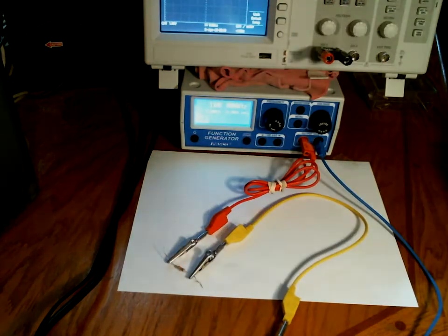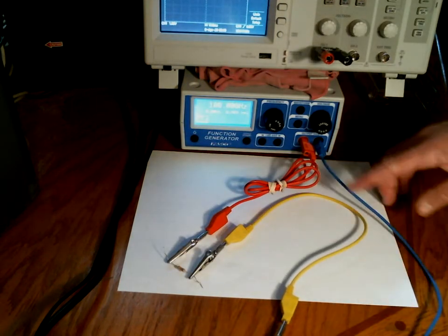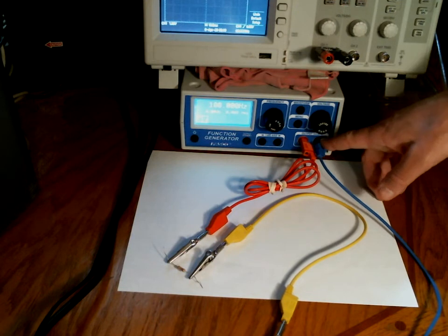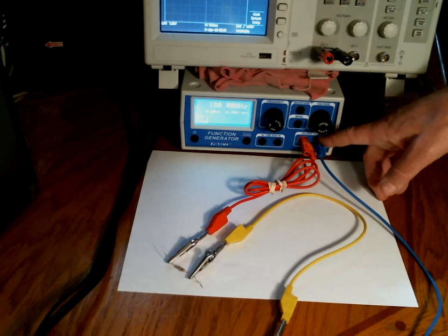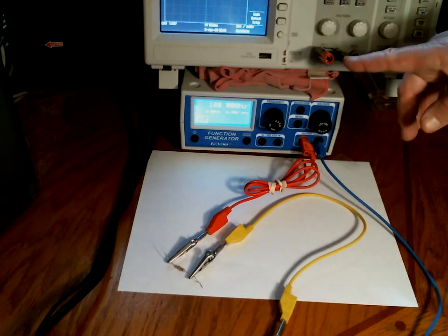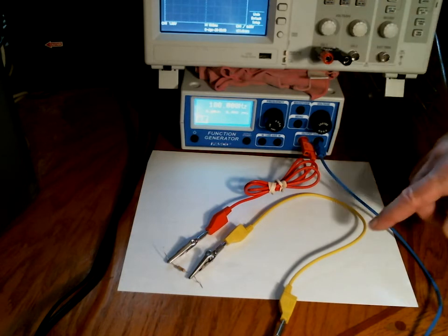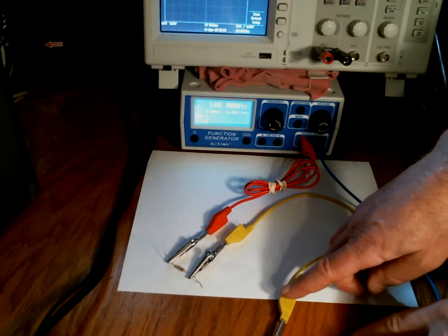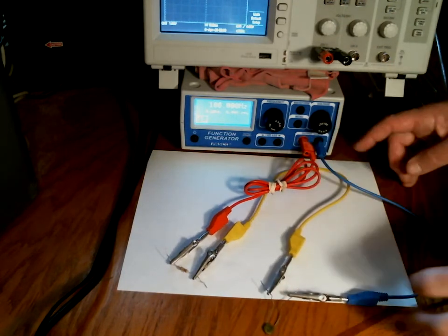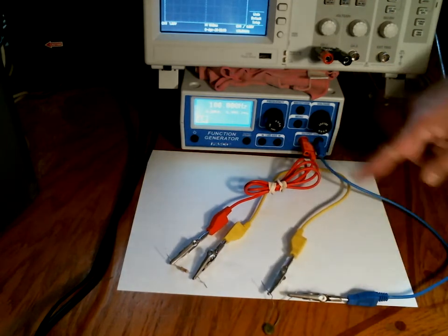And now, because this blue wire is the one that I hooked to the black grounded output of the function generator, I'm going to be constrained. No matter what I try to do, I'm going to have to send that to the ground on the scope, which means that really right now I'm set up appropriately in order to measure the voltage difference across the capacitor, because I'm constrained to have one of my connections here on this blue wire.